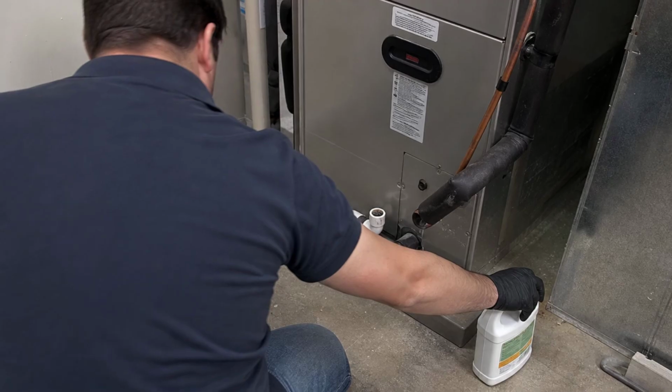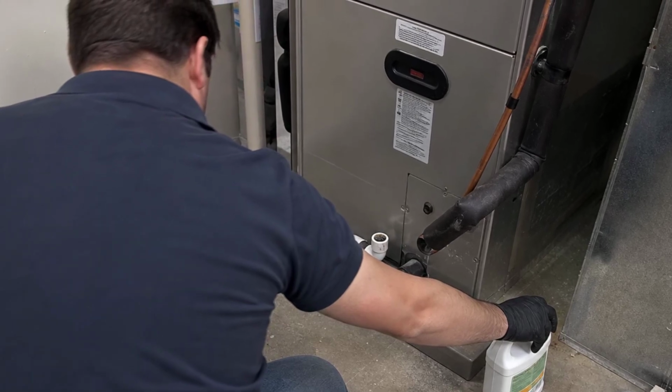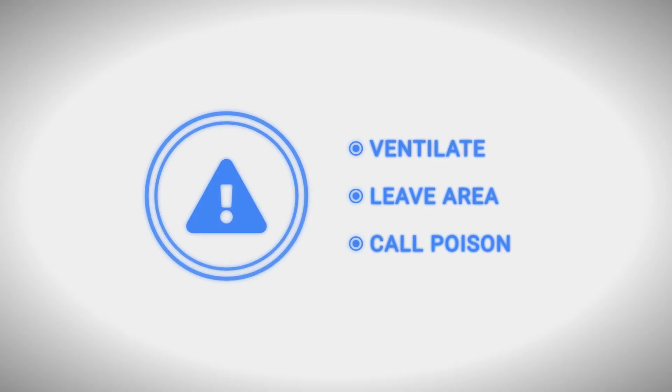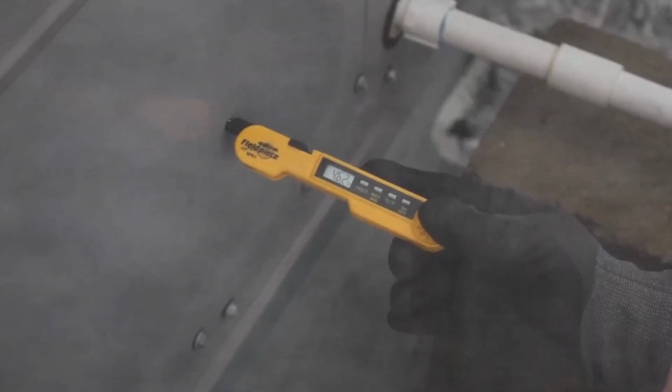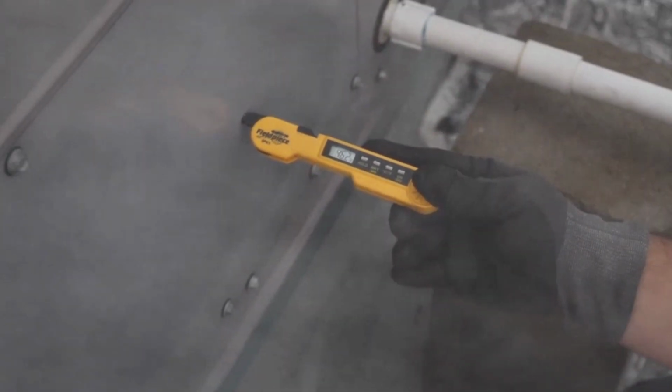If the previous chemical is unknown, stop adding products. Ventilate and leave the area if you encounter a strong unexpected odor or irritation, and contact poison control or the appropriate professional for the actual exposure. Do not lean over the opening to identify a gas by smell.